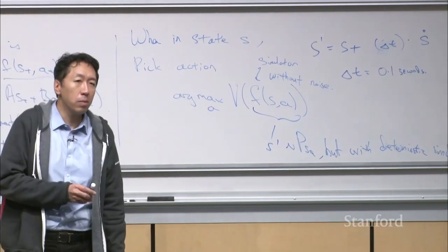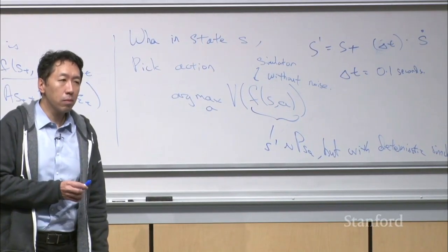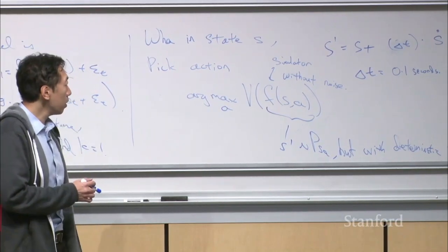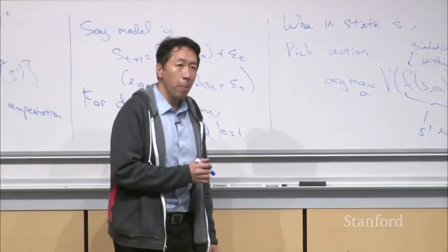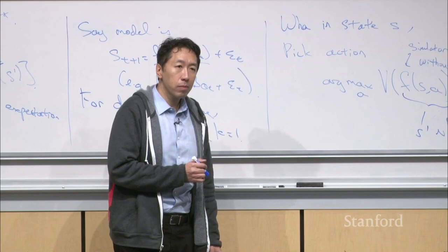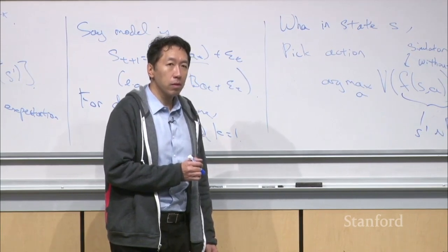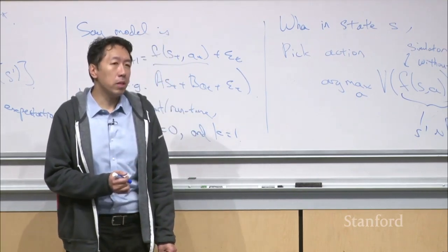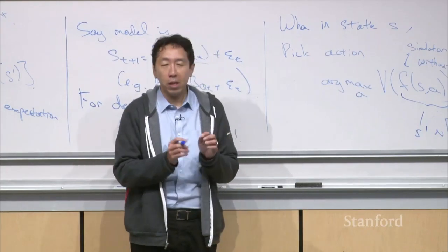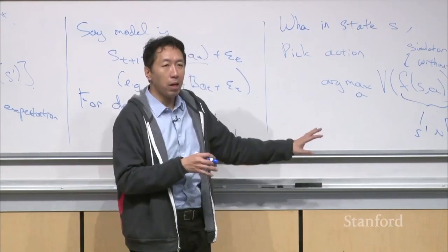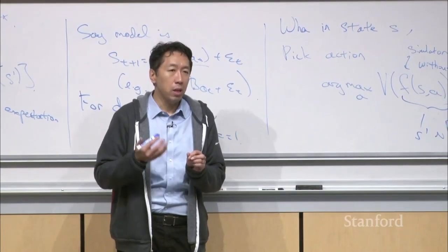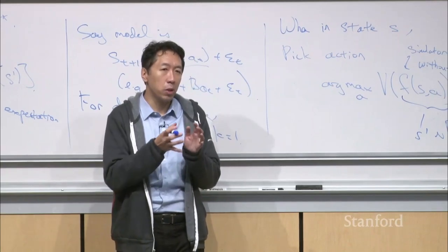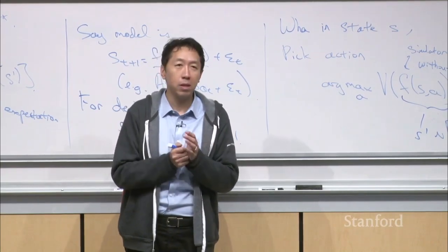Just one last question. So once you take that action, you transition to the next state. So how do you know what next state you're in? Do you make an observation, or do you use the S prime that you computed? Oh, I use an observation. Yes. So you take an action, and then your helicopter will do something. There'll be some wind. Your model may be off, and so you would then, a 10th of a second later, take another GPS reading, accelerometer reading, magnetic compass reading, and use the helicopter sensors to tell you where you actually are. Okay, cool.